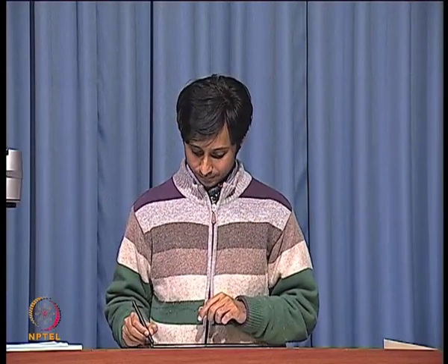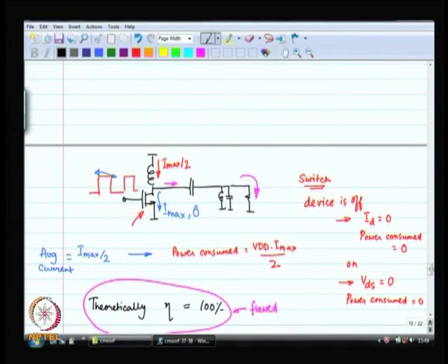So, what we have got is a power amplifier that is horribly nonlinear. Okay. Your input signal over here and the output, the relationship between the input and output is not at all linear, which means that if the input is a perfect sinusoid, your output will have a lot of harmonics.